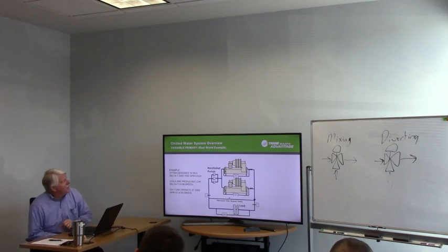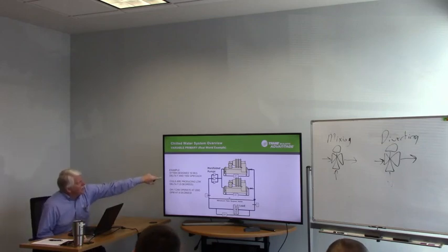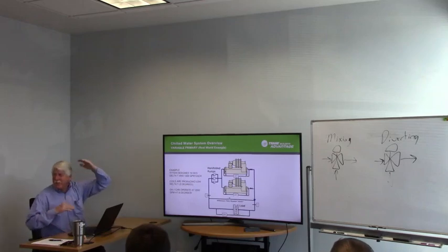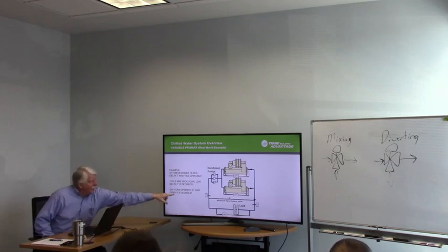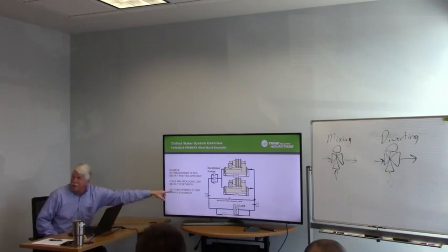The system is designed so that chiller can handle 1,000 GPM and do 16 degrees worth of work. Well, if the load out there is only 8 degrees, can I then change the GPM to 2,000 GPM and the chiller will work?